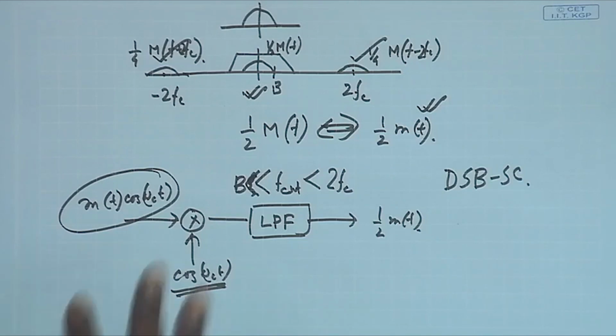So, that is the difficulty we have in this particular modulation scheme: we need another carrier which is completely in synchronism with the incoming carrier frequency and phase. This is the one difficulty that we have. That means the receiver design becomes a little more complicated, because we have to do this carrier recovery on top of this whole thing, right.